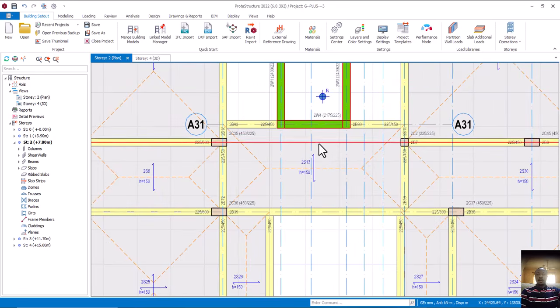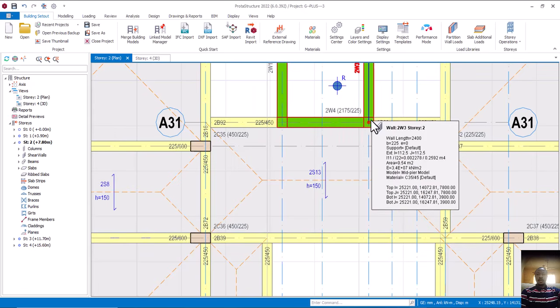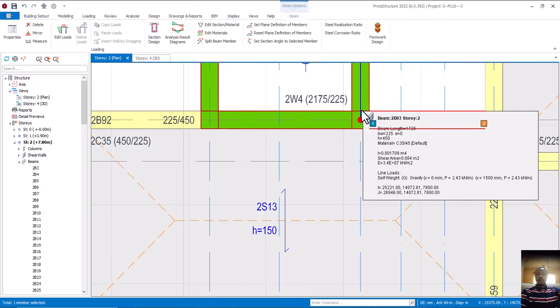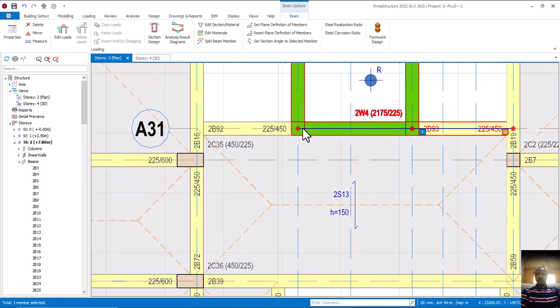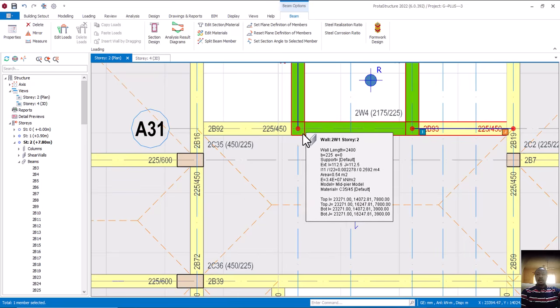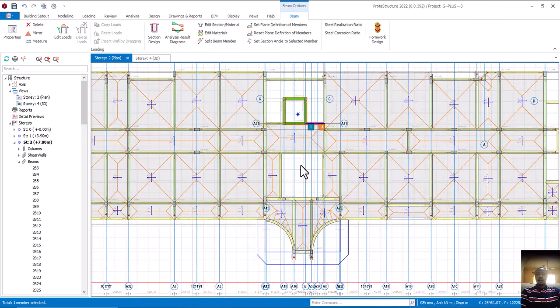Okay. Last time we were supposed to hinge this place. Can you see? We're supposed to hinge this part that is resting on the shear wall. This particular part needs to be hinged because it's not meant to carry moment. Is that okay? Around this place, if you do not release it, it can really cause a failure on this, which in a real sense is actually sufficient to carry this particular beam. Is that okay? All right, so that is that.